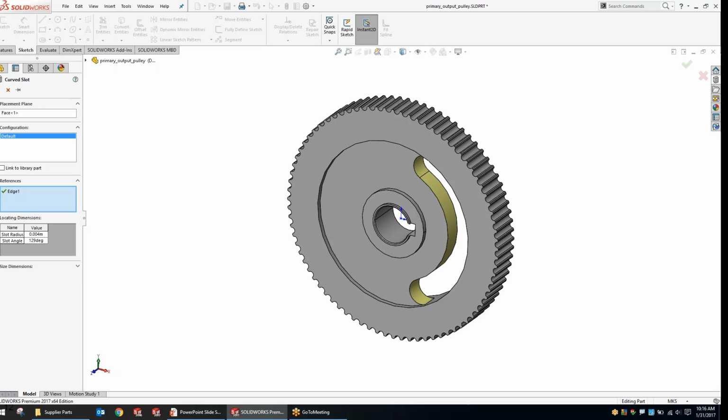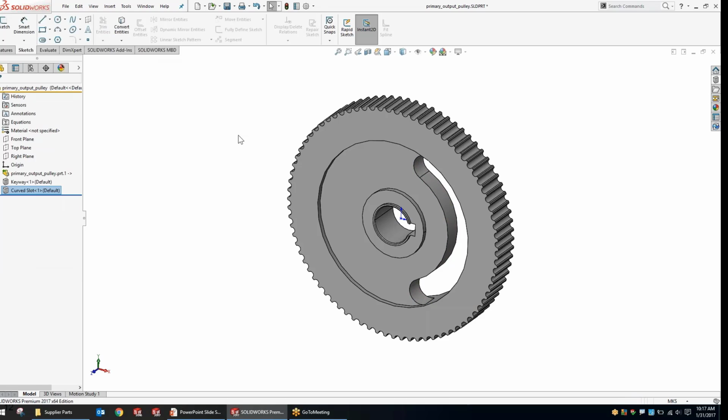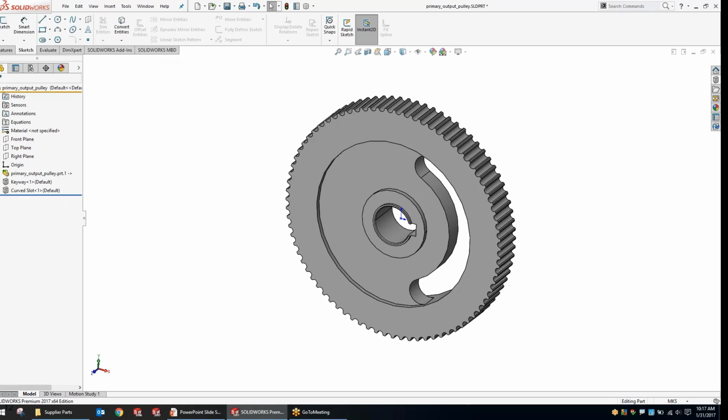So if you're maybe simplifying your master level assembly with a multi-body part that won't take up as much memory when you run that master level assembly, you won't have to worry about losing those mates, losing those dimensions on the drawings or the balloons with that type of transition. But with 3D Interconnect here, we went ahead and created our derived part and added a couple features ourselves, again using those faces and edges with some design library features.